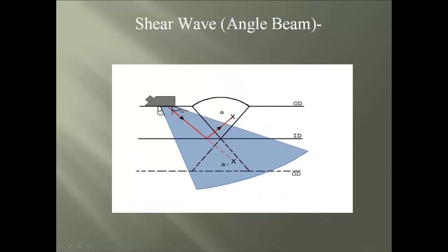Second, we look at the shear wave, also known as the angle beam, which is used widely for weld compliance due to the fact that it sends the sound into the part at an angle, allowing testing to be performed without the need for removal of any weld roughness.